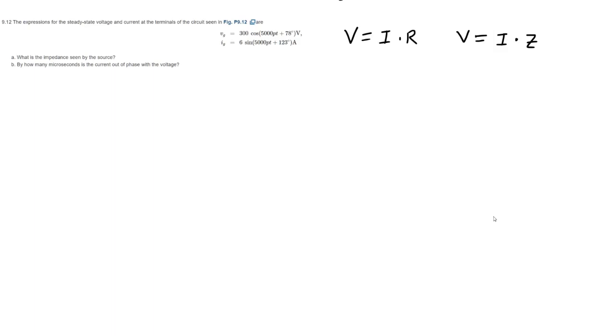You may remember when we were trying to find R Thevenin and R Norton, you did a ratio of a voltage and a current. You'd see that sometimes whenever you couldn't simplify the circuit into a resistor network because there's a dependent source. Well, you can do the same thing here. Z is going to be V divided by I, just like V over I.